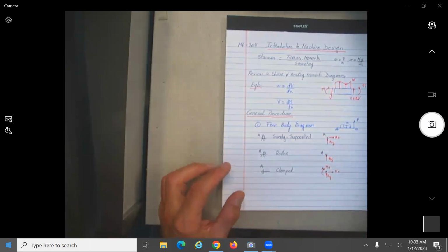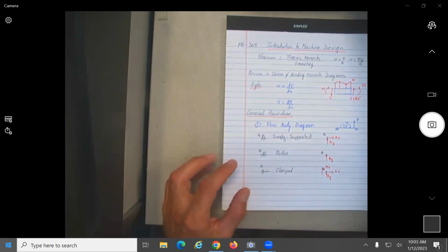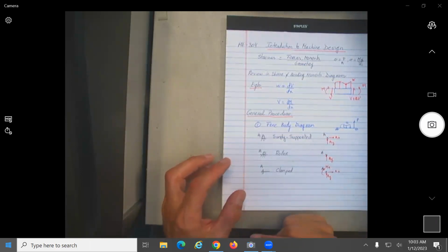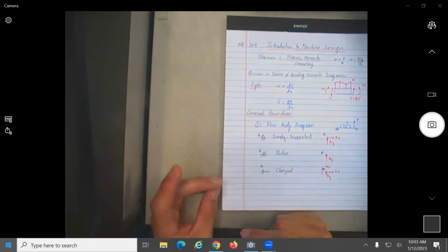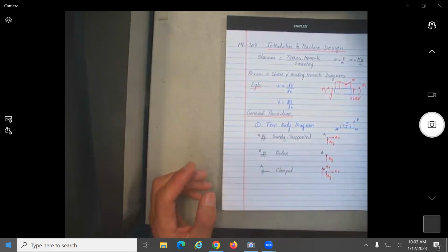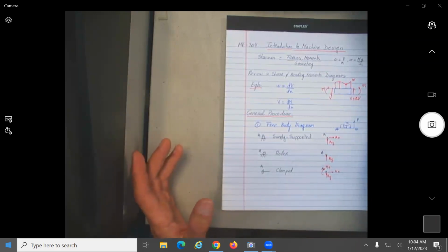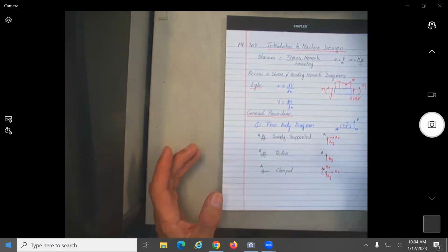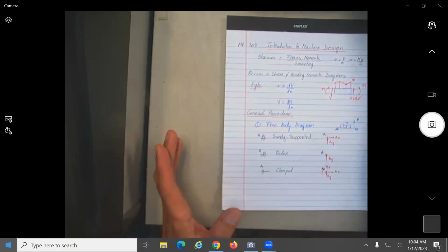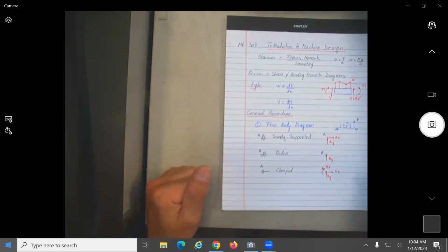So the problem is statically determined with 3 unknowns in 2 dimensions. Why is it 3? All right, so we have the summation of forces equal to 0 on the X and Y, and the moment equation on the Z. So basically, probably every single problem you have in here will be statically determined, but sometimes we do statically indeterminate, okay? So all the problems will be statically determinate.